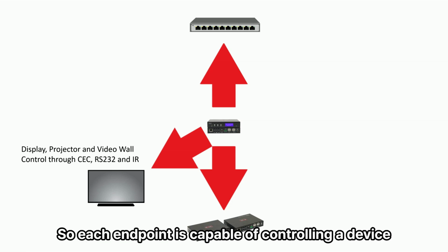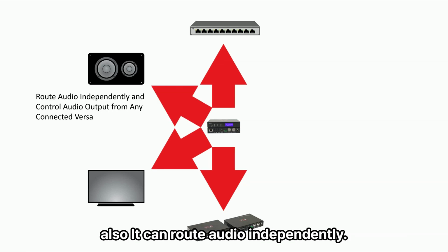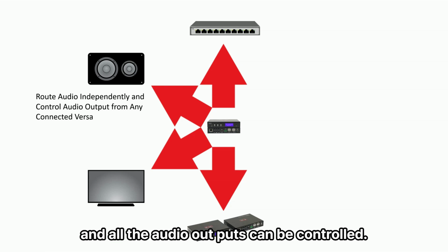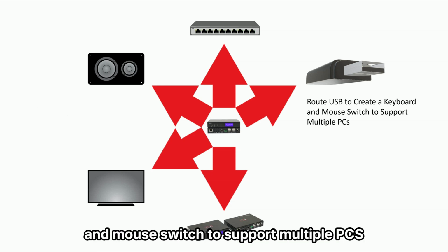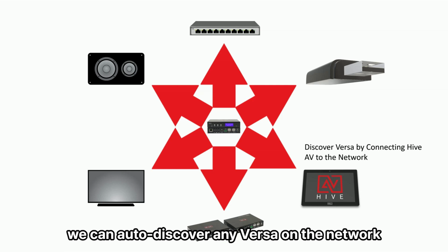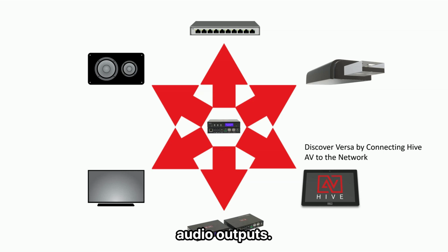So each endpoint is capable of controlling a device over IR or RS-232 or CEC. That's just from the HDMI cable. Also, it can route audio independently to any of the decoders, and all the audio outputs can be controlled. You can also route USB to create a keyboard and mouse switch to support multiple PCs. It goes with the Hive AV App and the Hive Touch. We can auto discover any Versa on the network, automatically create a very simple, easy to use matrix interface, and create control for any displays and for the audio outputs.